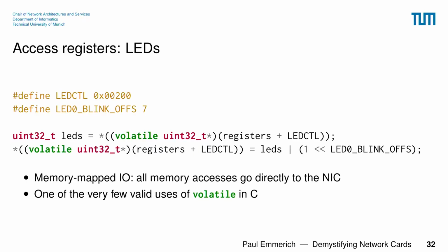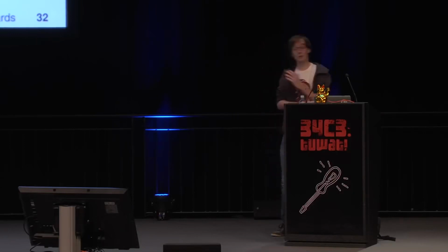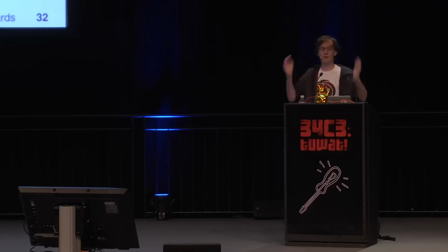And one thing to note is, since this is not memory, that also means it can't be cached. There's no cache in between. Each of these accesses will trigger a PCI Express transaction, and it will take quite some time. Speaking of lots of cycles, where lots means like hundreds of cycles, or 100 cycles, which is a lot for me.